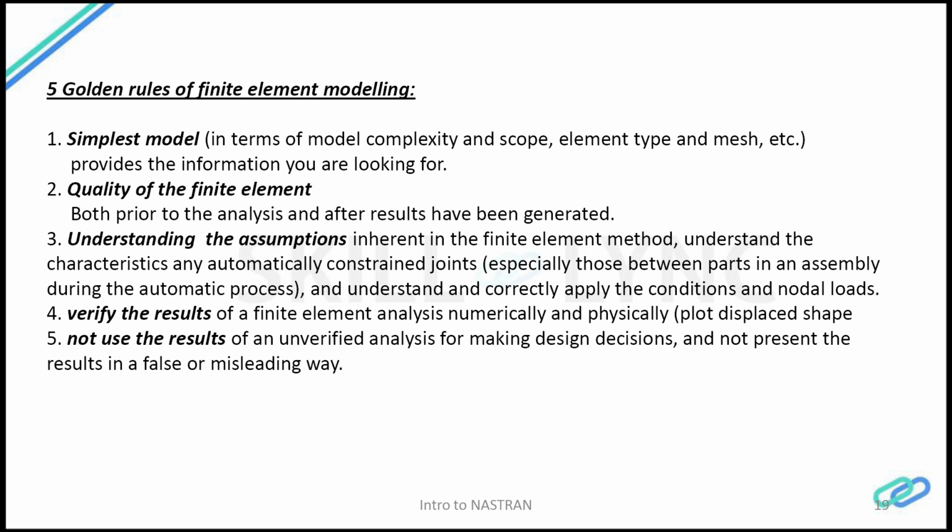Suppose the finite element tools give you a stress of 200 times 10 to the power 8, you should be really suspicious about why such a very high value of stress comes into the picture. So what is the mistake I have done? You have to go back and dig into the mesh, dig into your assumptions of the boundary conditions, to check whether you have properly represented the actual phenomena.